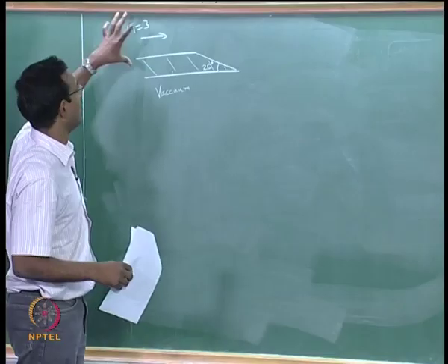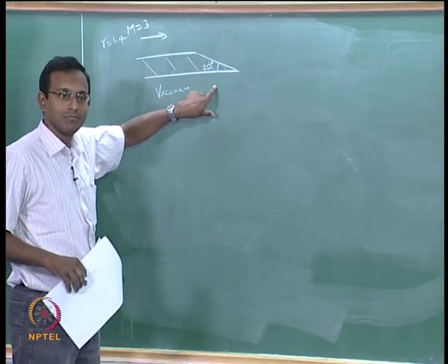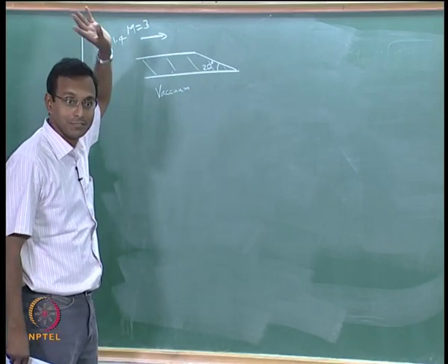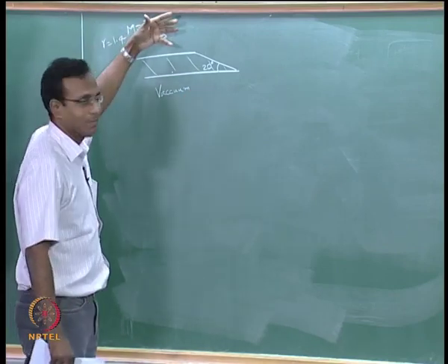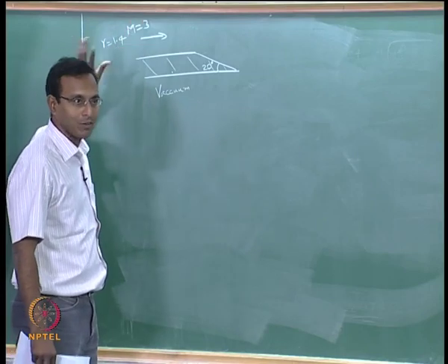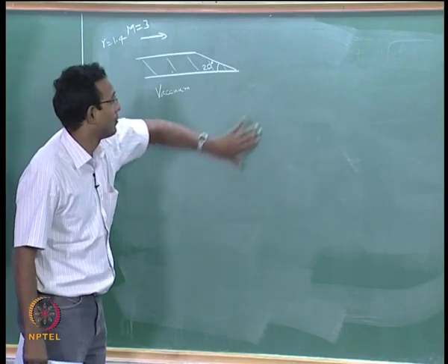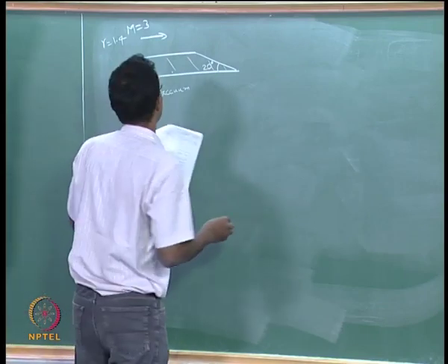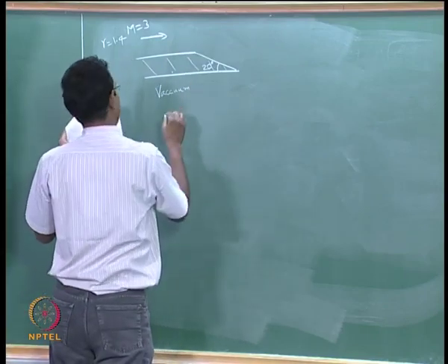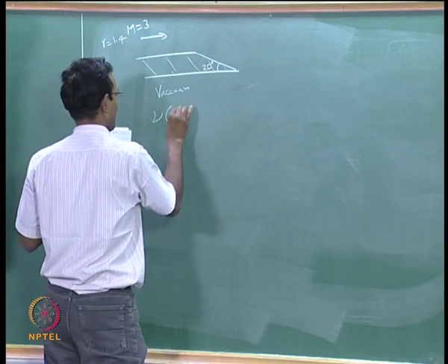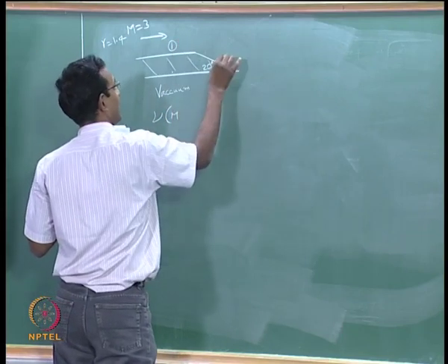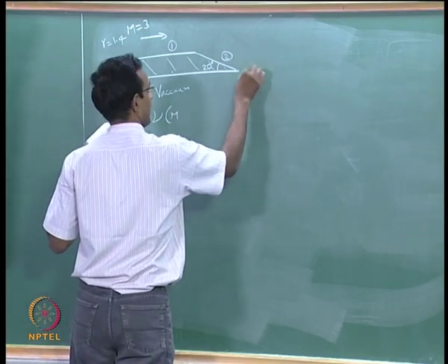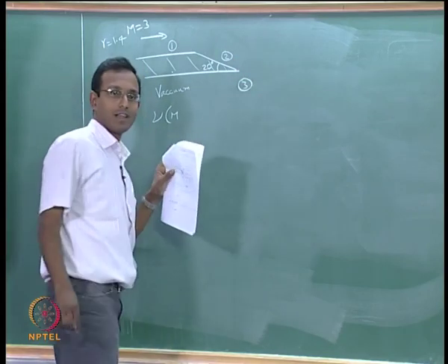Let us say this is my nozzle exit from my rocket and it is sitting in space. Currently the flow coming out is M equal to 3 at gamma equal to 1.4, and I want to see what is the flow field here. That is the idea. If I think about it that way, what should I do? I will just go faster this time. Nu of M equal to 3, I will mark this region 1, this region is 2, and somewhere outside is 3.